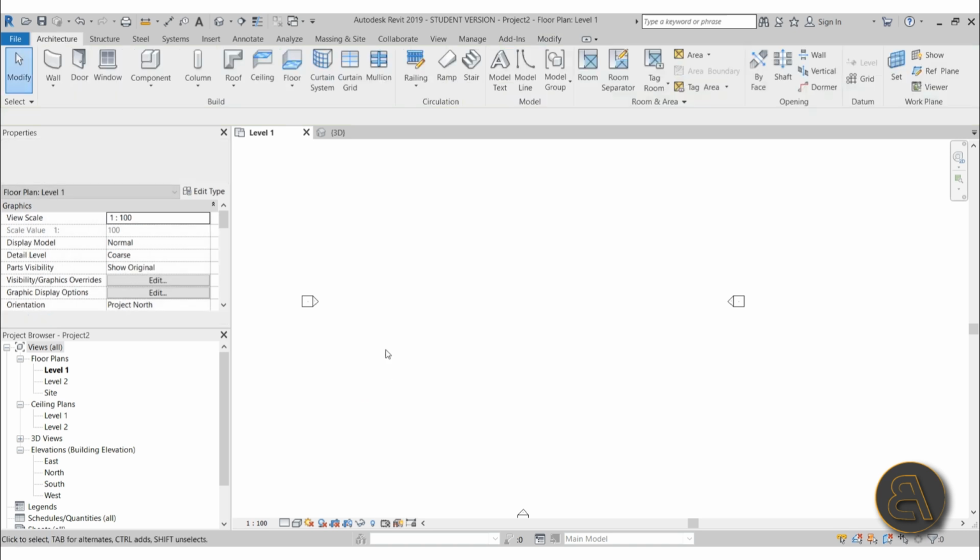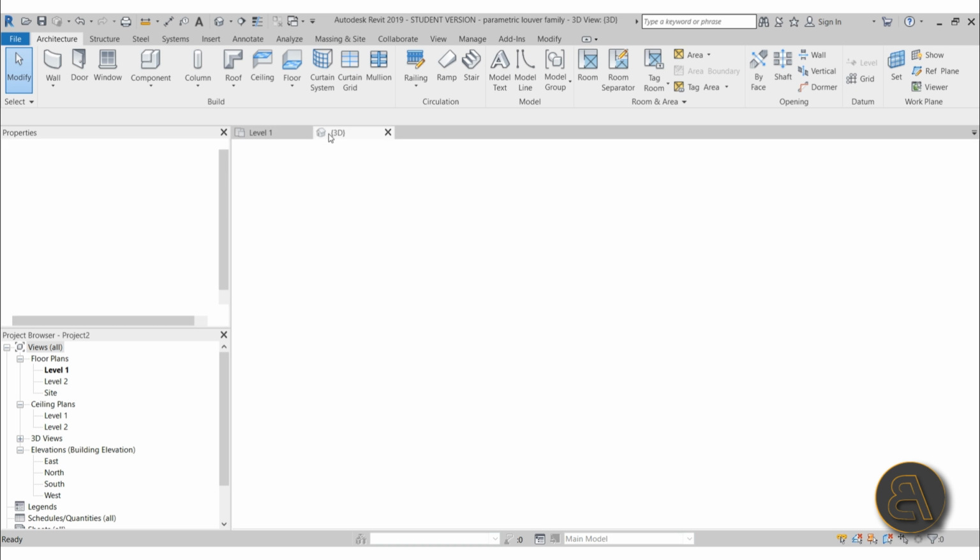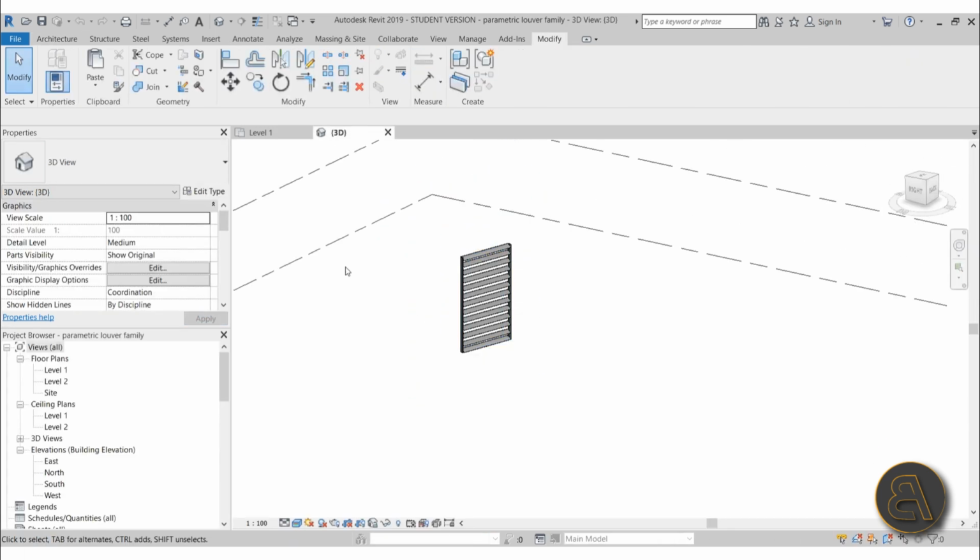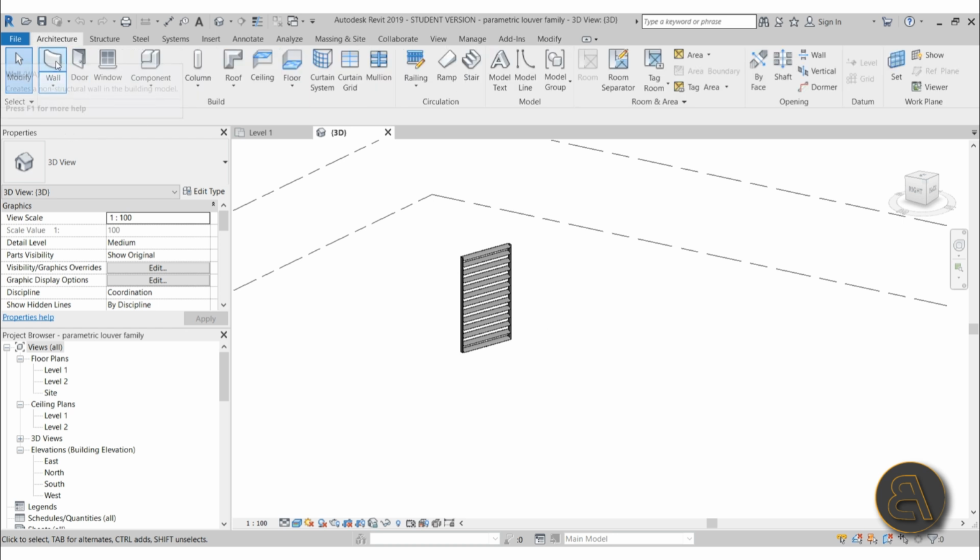So that's basically the only way you can share these families between files. Alternatively, you can create a template that holds all of these, or sometimes I've seen people stack up more of these walls, so they create some system families like walls, stairs or railings. Here we have walls that are system families, we have roofs, floors, curtain systems, railings, and stairs.